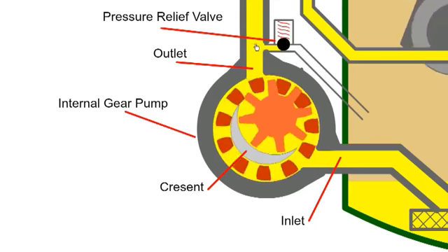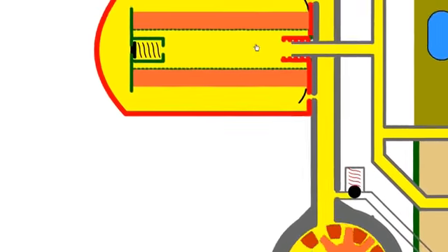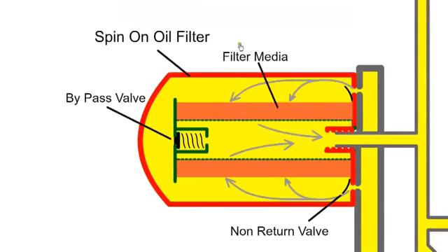As the oil lubricates the engine, it will pick up dirt particles which are removed by the filter. Early filters consisted of a housing and a replaceable cartridge filter. Later manufacturers introduced spin-on filters, which were easier to fit. However, recently the trend is back to cartridge filters, which are considered to be easier to dispose of. This is a spin-on filter.